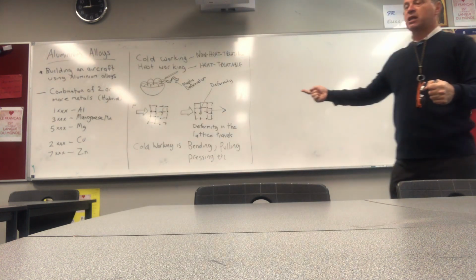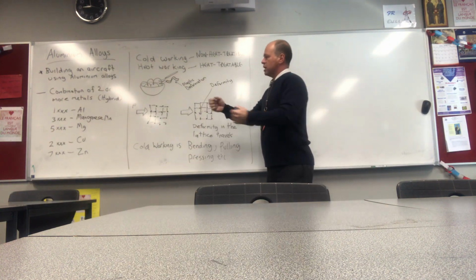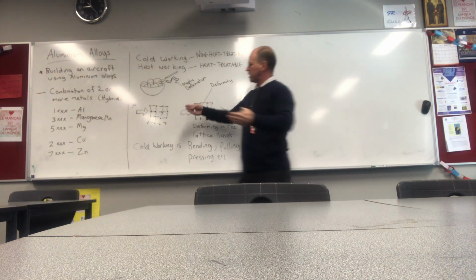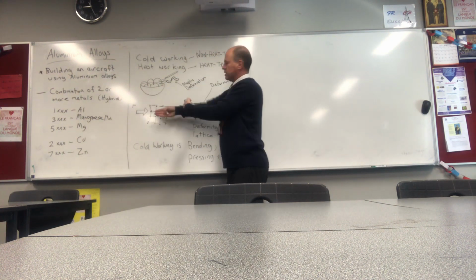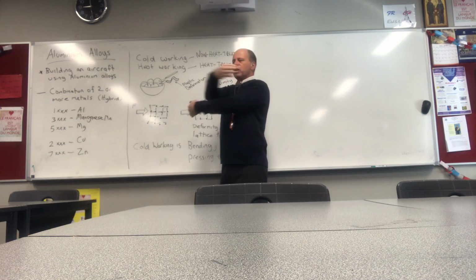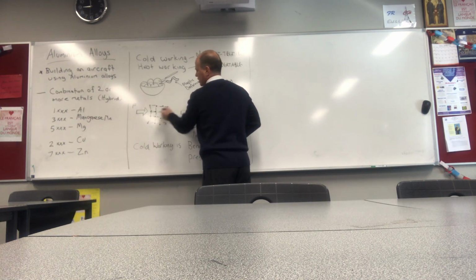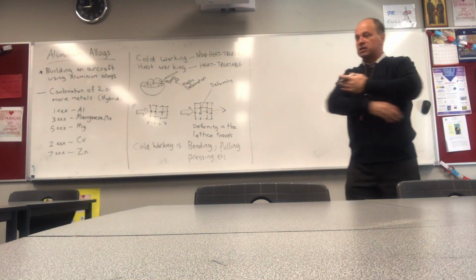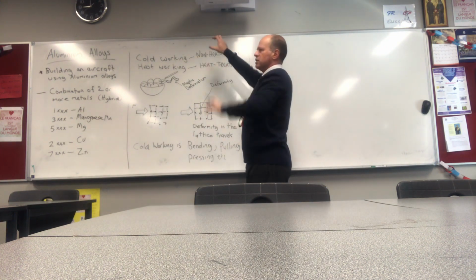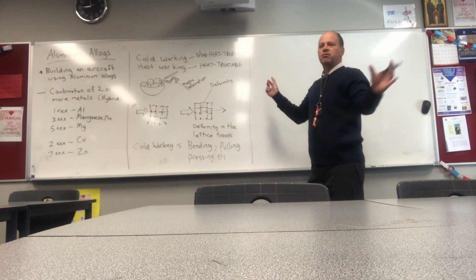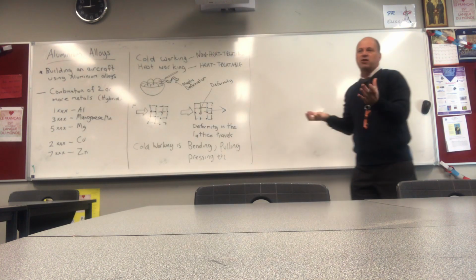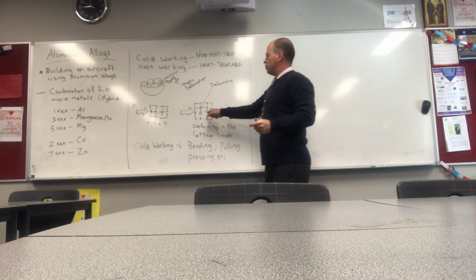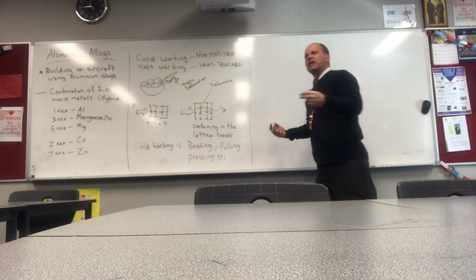That's cold working, okay? What happens is these deformities move across, and if you've got a perfect lattice like this, it's able to slide across itself quite easily. There's no obstructions, okay? So it'll tend to shear across these boundaries, and you've got this lovely smooth transition happening, so it's really easy to work. But when you've got these deformities, these little lumps all over the place that have travelled across from various places, it creates a traffic jam essentially, and it makes it very hard for the material to move. So once you start these things moving in all different directions, they get in each other's way.